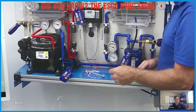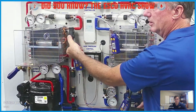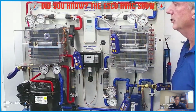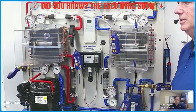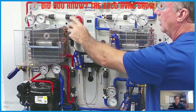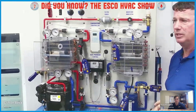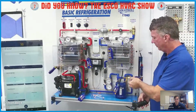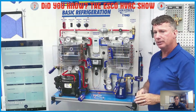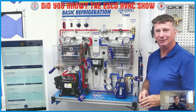And then on my high side, right above it, on the liquid line coming out of that condenser, I've done the same thing with it. And so it's easy to be able to find a good location, and keeping those visuals is pretty handy. That way all of our tools are the same color. Because I've noticed too, Eric, with all of your instrumentation, they come with red and blue indicators for each tool so that you can mark which one is going to be used consistently on the low side or low pressure of each connection.